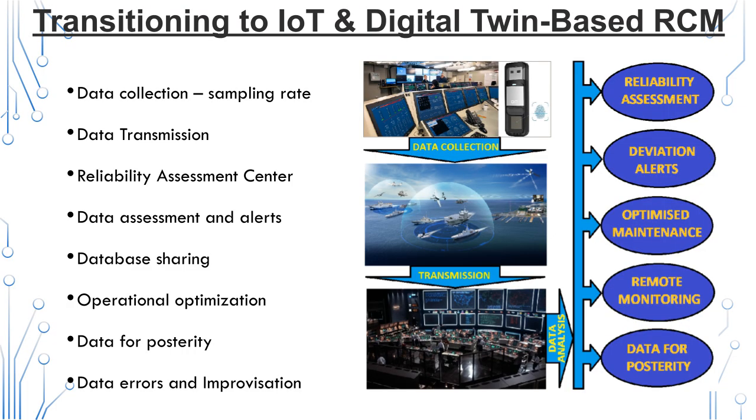IoT sensors capture equipment operational data such as temperatures, vibrations, pressure, and oil quality. So this real-time monitoring provides immediate insights into the health and performance of the naval assets, supporting timely interventions. The data is relayed to IPMS, that's the control systems, and saved as per the chosen sampling rate, which could practically be 15 minutes. Ships without this kind of management system can target the main machinery like propulsion and power generation through their local control systems. This data is saved and sent out of the ship securely on a daily basis.